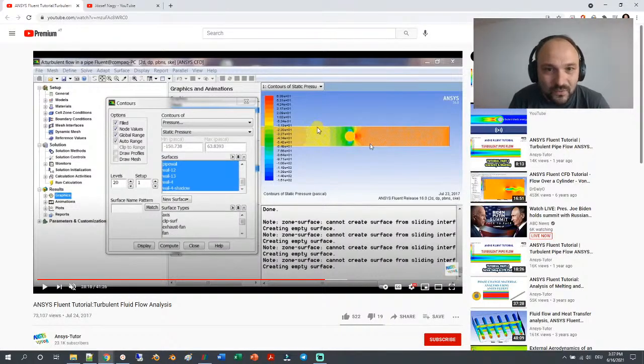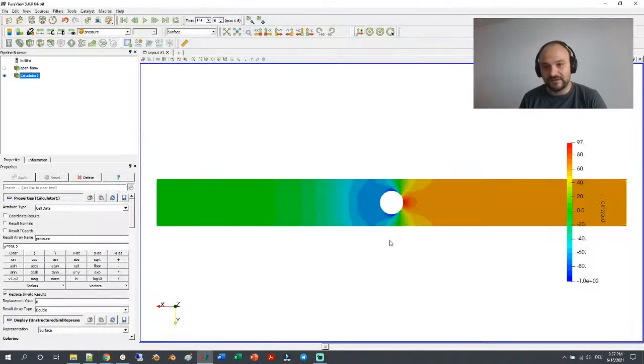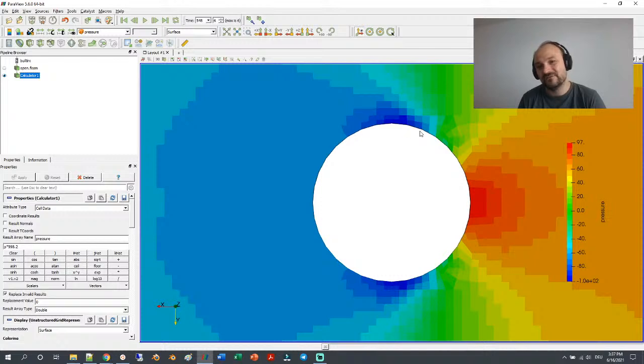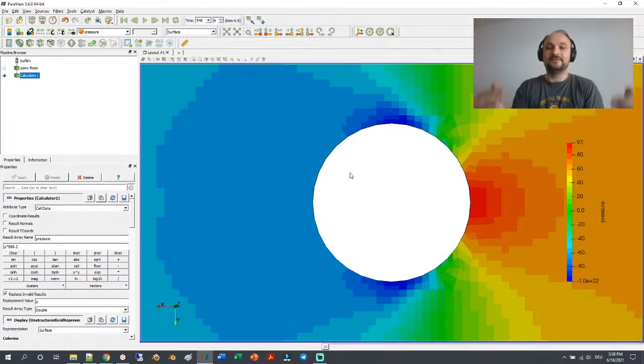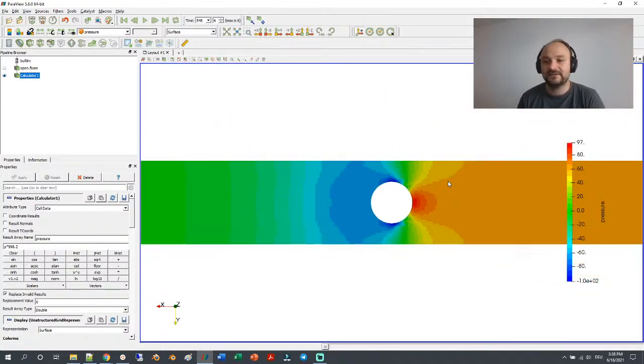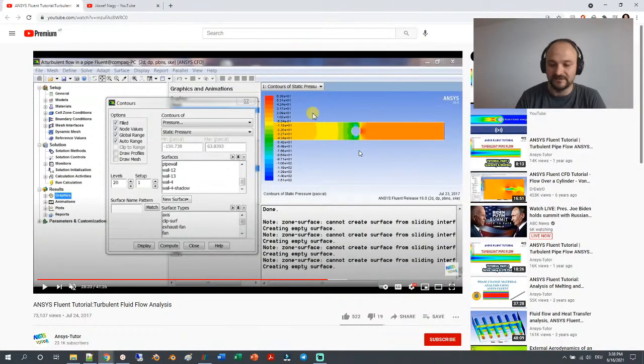What I am not 100% sure about is, okay, it is converging towards 0. So here he sees somewhat lower pressure values on the top and the bottom. Maybe if I refine the mesh here, so feel free to refine the mesh and add some layers here manually, and then see whether you can get a better value for the pressure minimum here. But qualitatively it's the same.